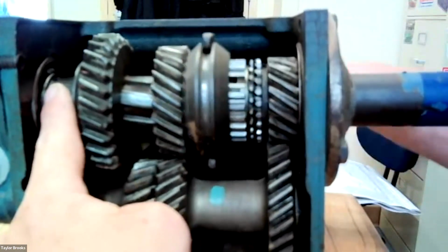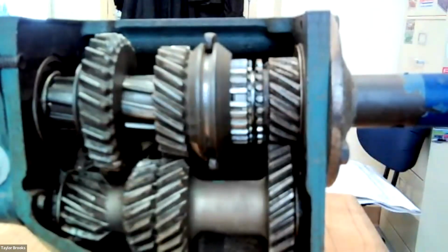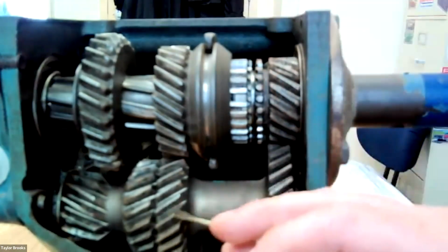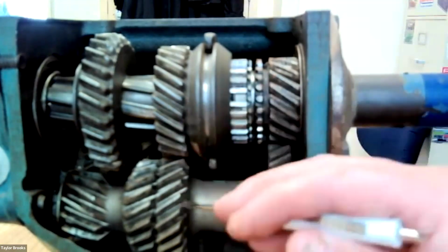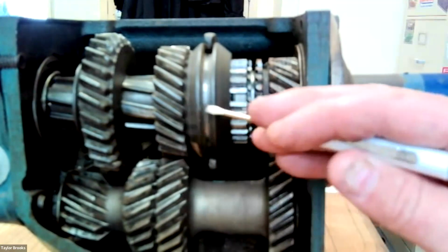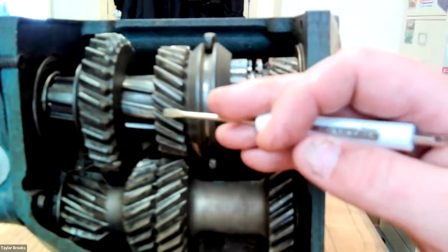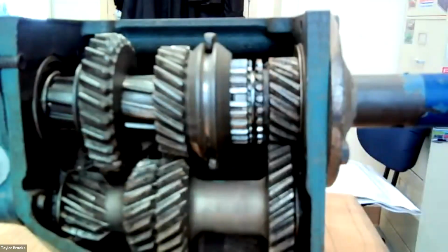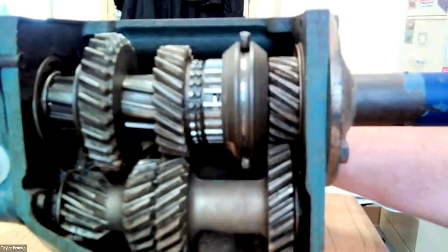Now, when I lock it into second gear, I now can't hold it. Power is transferring from my input down to my counter shaft because the counter shaft is in constant mesh with my second gear right here. It is always turning this, but what I've done is I've locked it with my synchronizer, and that has locked the speed gear to our output shaft, and that's going out and driving our drive shaft at this point. And then when I shift into third, it's just as smooth.